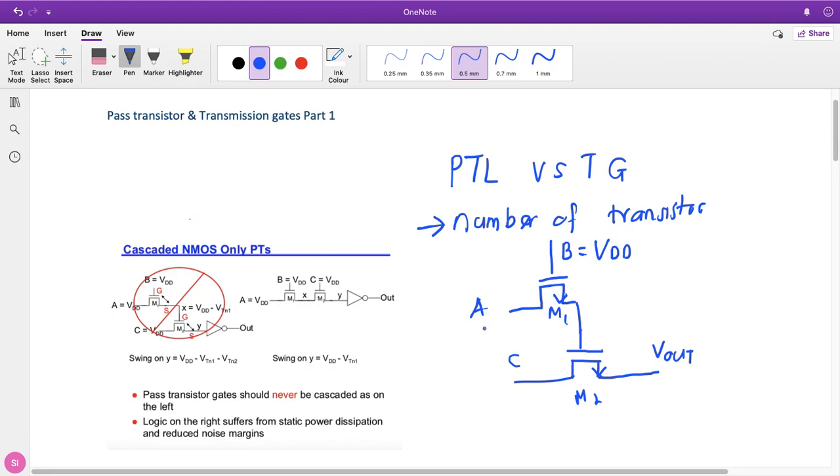So this cell will be activated whenever this NMOS gate is in on state. Here it's clearly seen that this NMOS is on, where B as a control input is set to VDD. Therefore, the Vs, I can call this Vs or I can call it X, is equal to VDD minus VT.